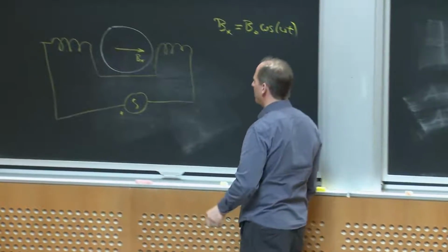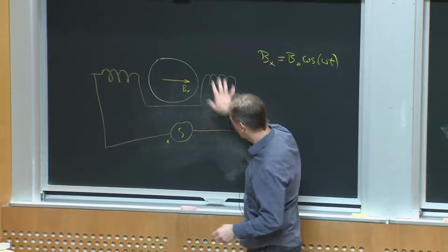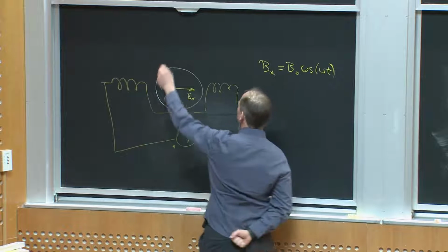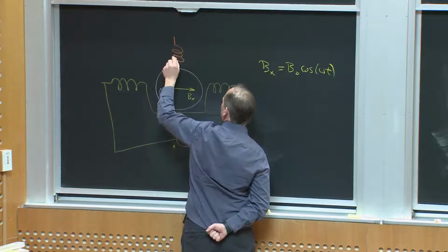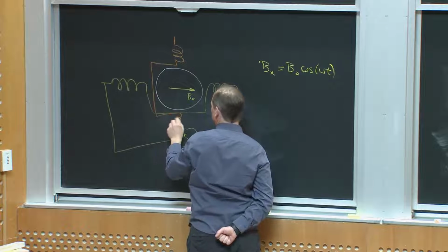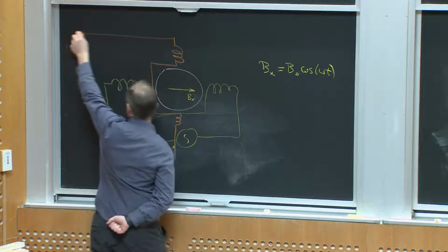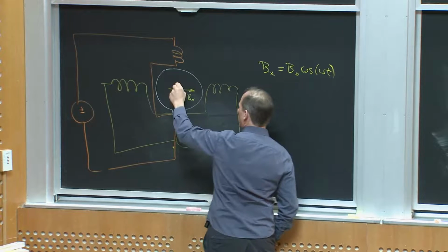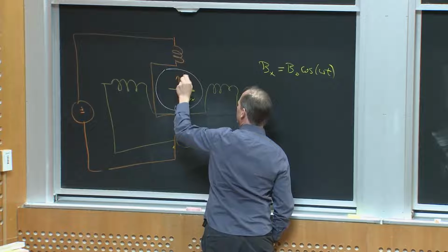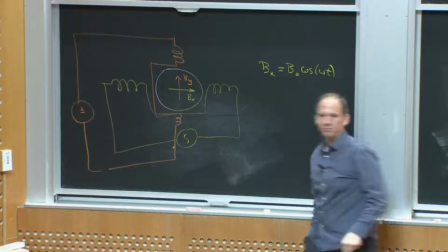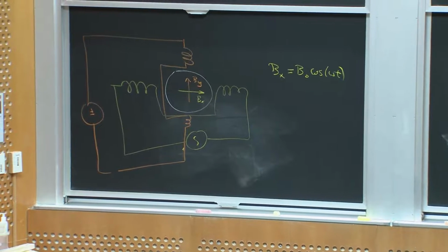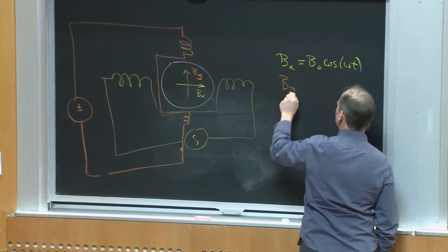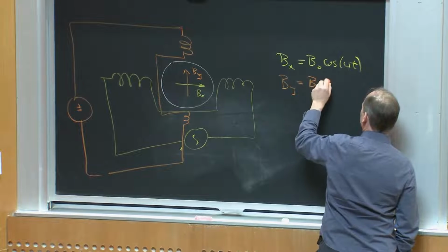But imagine I came and said, all right, that's one phase, right? This could be a sinusoidal voltage I'm driving with. But perhaps I created a second one like this that's perpendicular to it. Right? And maybe with this one, I could create some y-directed magnetic flux density. Okay? Well, maybe the orange set of coils here could create B sub y equal to B naught sine omega t.